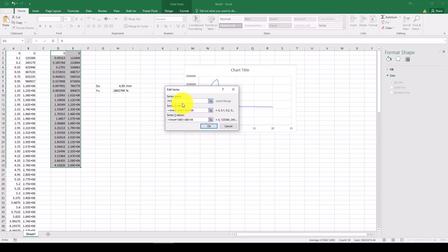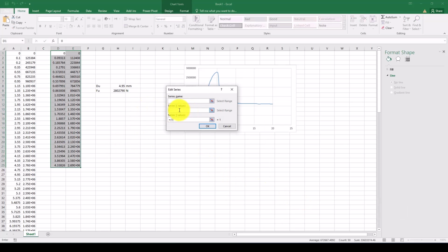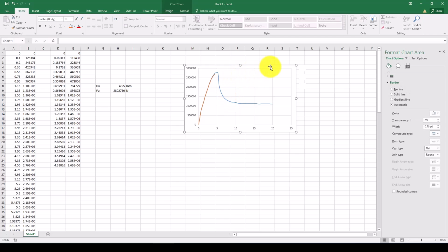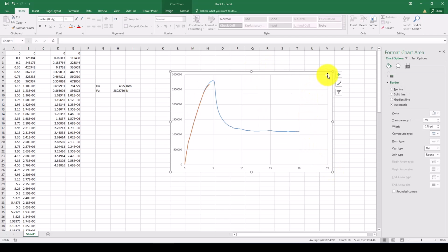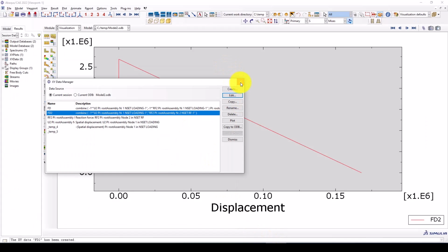If this is called FED1, and we want to get one FED2, so this is FED2, and here is the y. Now you can see this is the graph. When we apply the load to maximum at this point, the structure totally collapsed, and the entire elements, because of the shear damage, because of the concrete damage, were destroyed. Now like this.